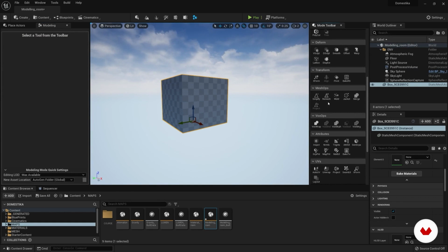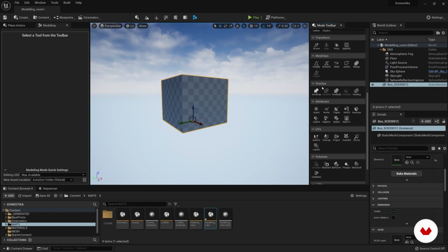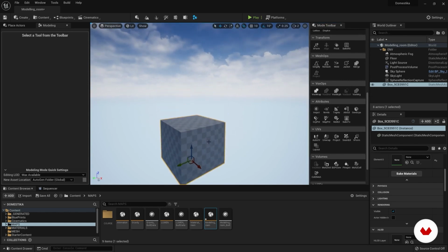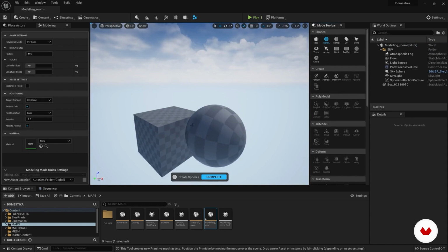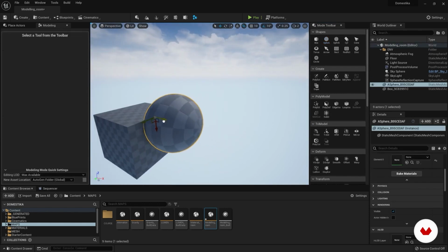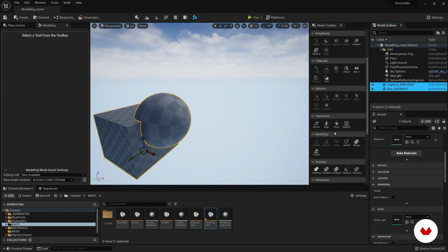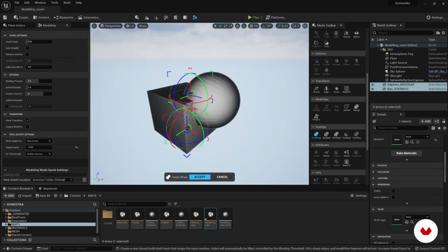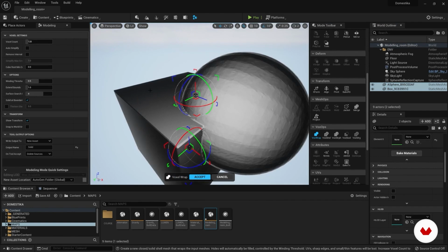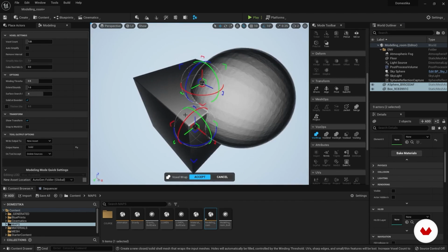Mesh Cleanup. We're not going to test it. It just serves to simplify the geometry, to automatically reduce the number of polygons. Remesh is used to increase the number of polygons, in case more density is needed to increase the details. Vox operator transforms geometries into voxels and then transforms them back into geometries. It won't be useful to us in our course. I'll show it to you just out of curiosity. See how it transformed the geometries. With voxel computation, it merged them and created a new geometry.